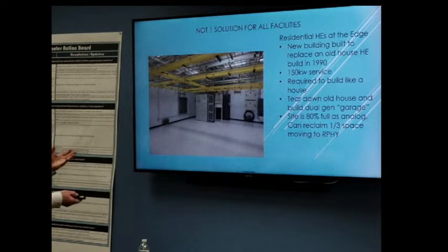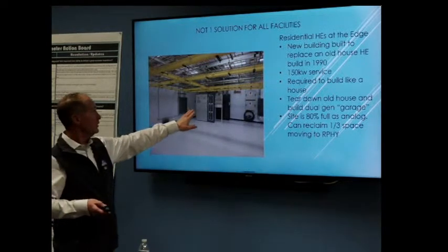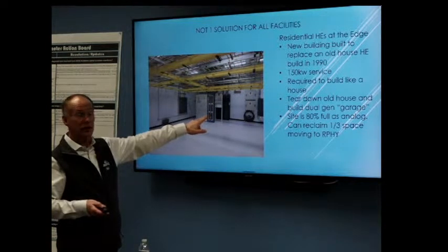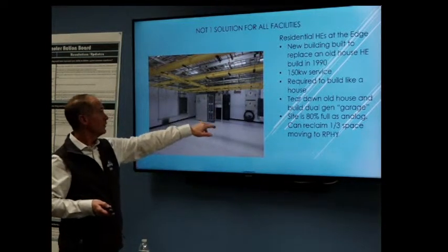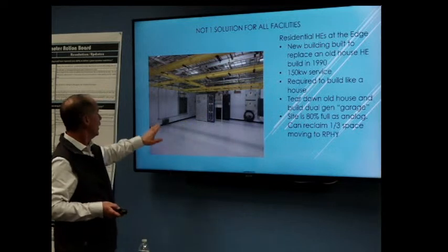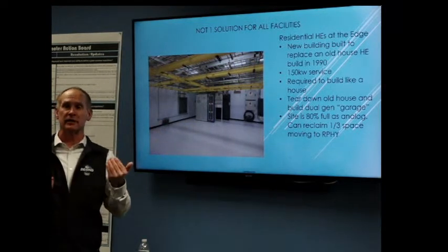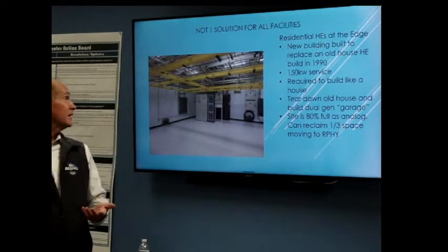Talking through some of the infrastructure that you're going to see typically in every site, you've got a DC power plant, a battery distribution circuit breaker bay, an inverter system, and batteries behind it. Obviously, infrastructure really can't do anything without some means of fiber connectivity.